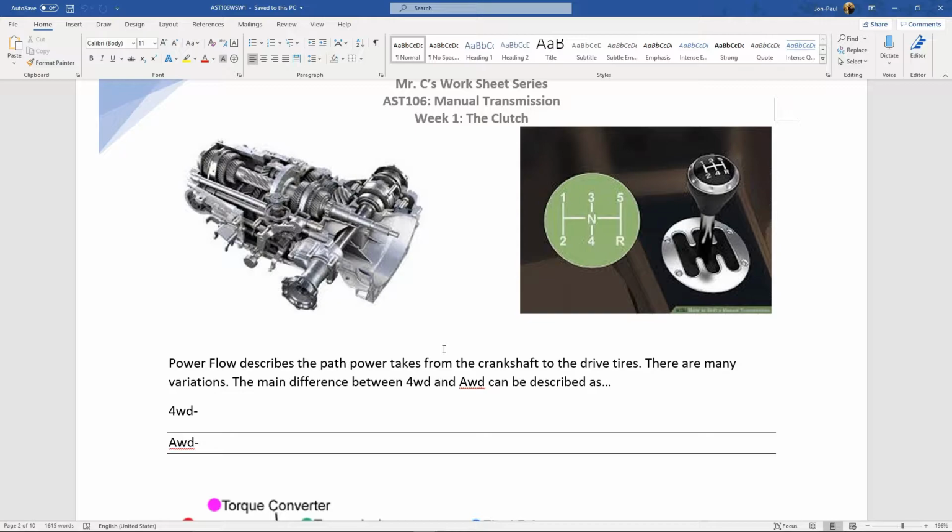The other is whether or not you can disengage it. So if we get in that Wrangler, we go engine, transmission, transfer case, and the transfer case has a drive shaft that goes backwards to the rear diff and a drive shaft that goes forward to the front diff. And that transfer case has several gears. It'll be neutral, 4 high, 4 low, and 2-wheel high. All-wheel drive vehicles normally do not have a means by which to disengage. So that lack of transfer case is another way you can look at it.